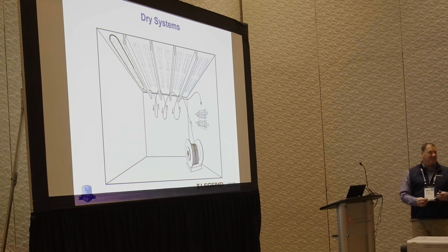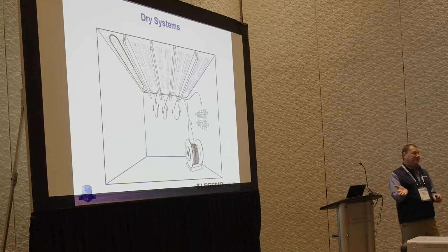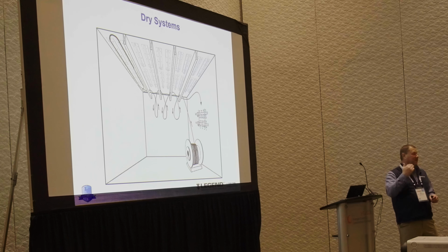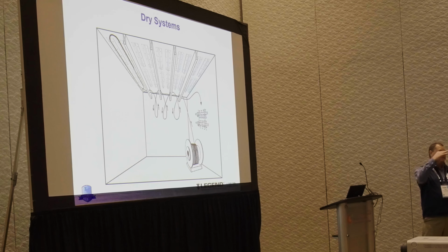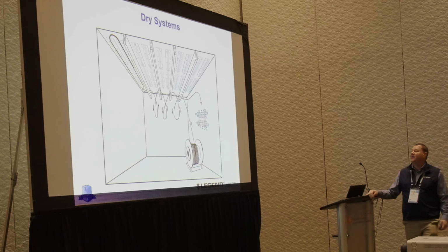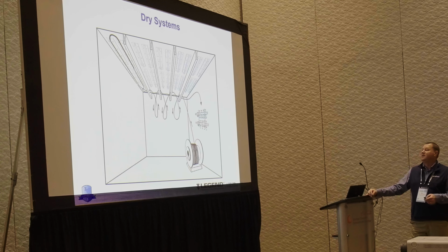Because the way a heat transfer plate works is it's in contact with the floor. It's in contact with the tubing, and it's going to conductively transfer its heat from the tubing to the plate to the floor. And if you got only 2 screws in a 10-hole plate, it's going to expand and contract. It's not going to touch the floor. You're not going to get great contact or conduction. So make sure you put your plates in there.